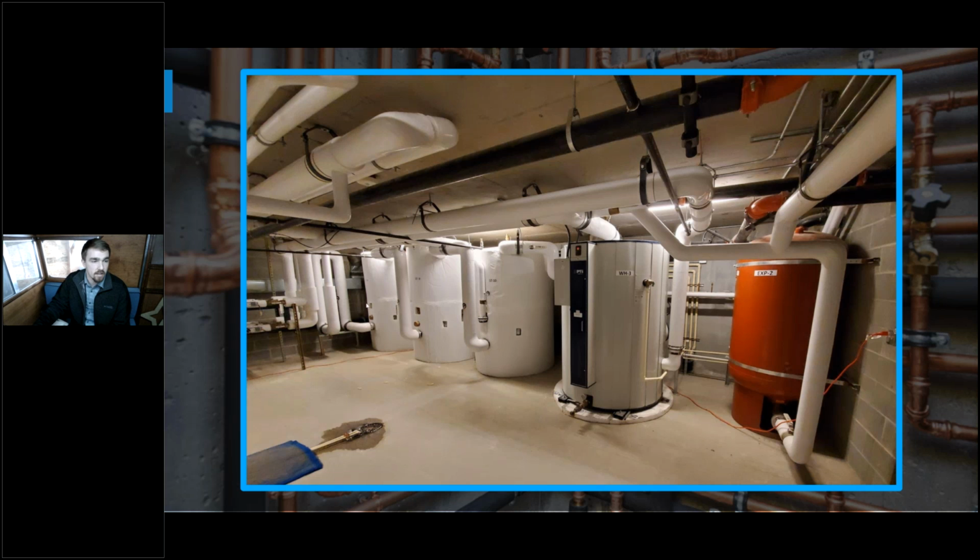So we see this plumbing, we see the top of the first tank go down to the bottom of the next tank, and so forth to the third tank. So you can picture these as 3 tanks stacked on top of each other because they're connected top to bottom and offering this one really tall stratified tank.